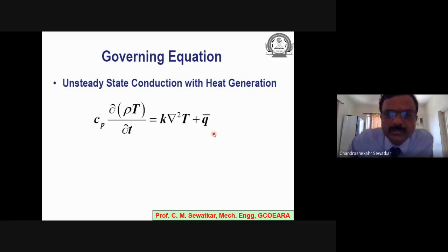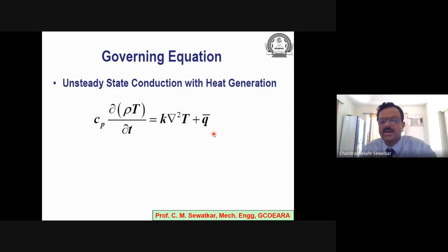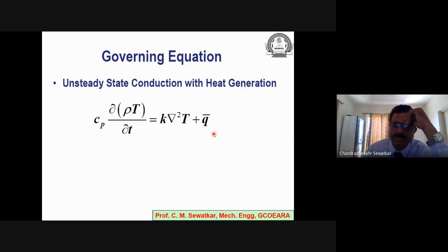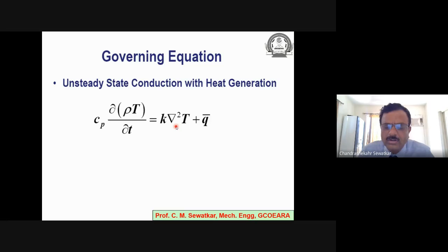What we will do is take up each and every term in this equation and try to apply it to a small control volume. We will discretize all the terms, and put all those terms together to formulate the entire equation. Once we have the entire equation, we will look at the solution methodology to obtain the solution for temperature. To remember, our objective in the unsteady state heat conduction problem is to obtain the solution for all the xy locations at all the time instances.